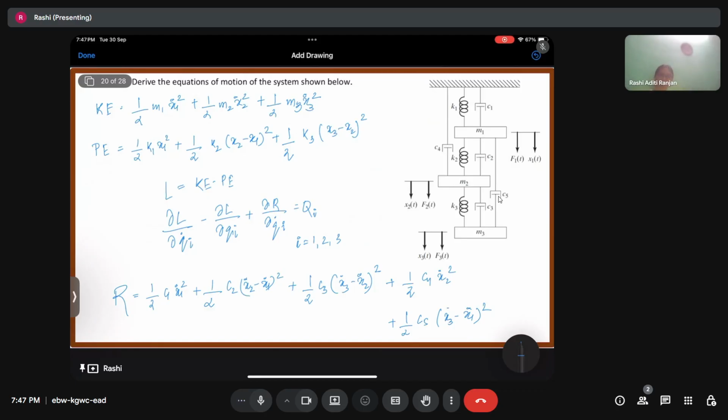Using that, we assumed the solution can be written as the multiplication of capital X, which we got from the eigenvectors, and Q, the solution of the uncoupled equation. We put it into the equation and found how to get Q. Q was an equation same as that of the single degree of freedom undamped system. We evaluated capital X, wherein we had two constants, and used orthogonalization to find the values of those two constants.